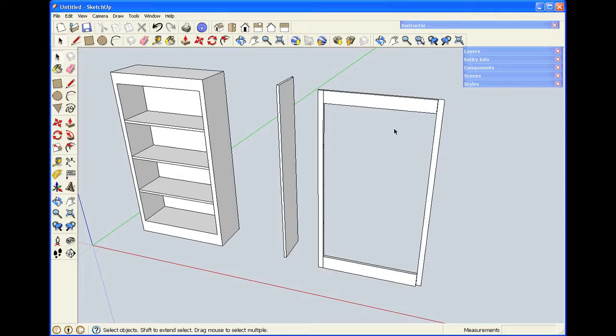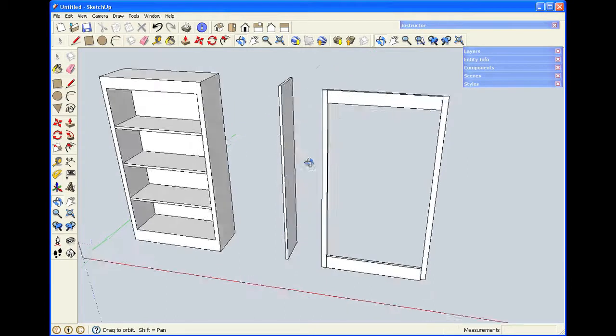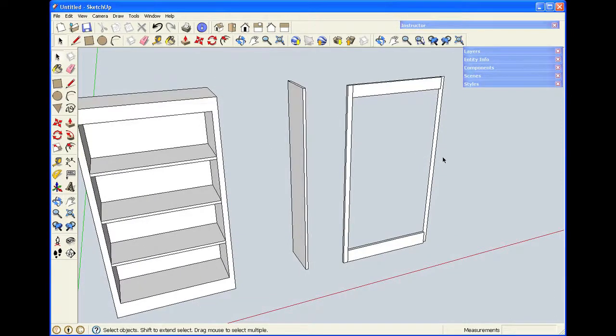and the two rails. When I build the cabinet, I want to set the shelves into dados in the cabinet side. Again, all the information I need, the spacing, is over here, and I could measure and redraw. I also have that same information available over here as the remnants of the lines on the other style. So I'm extruding this out to a 10.5 inch width, which should match the inside of the cabinet side.